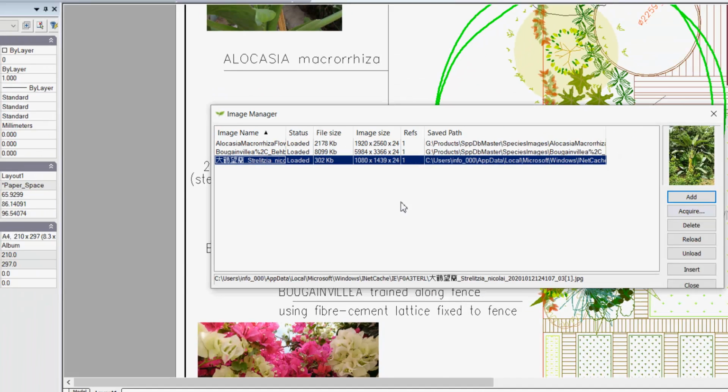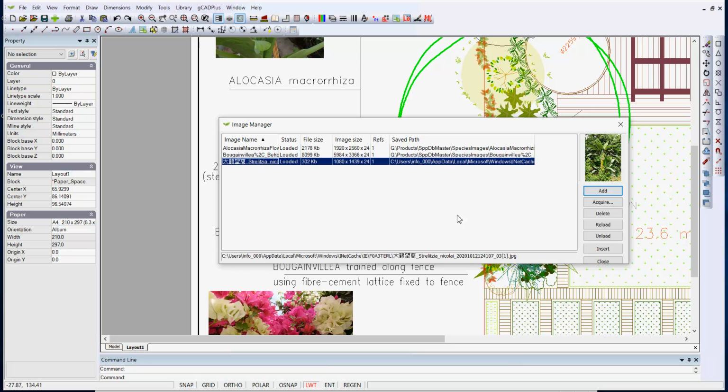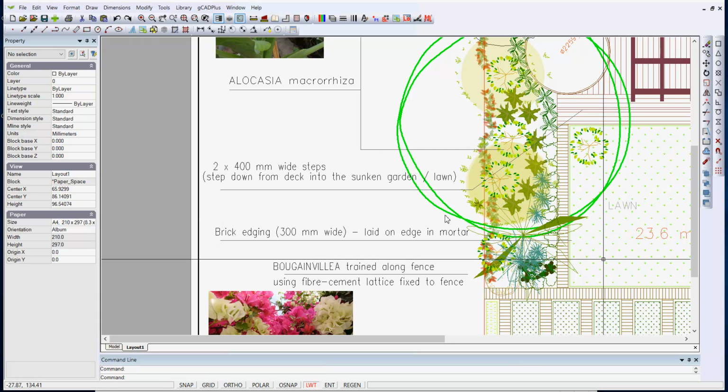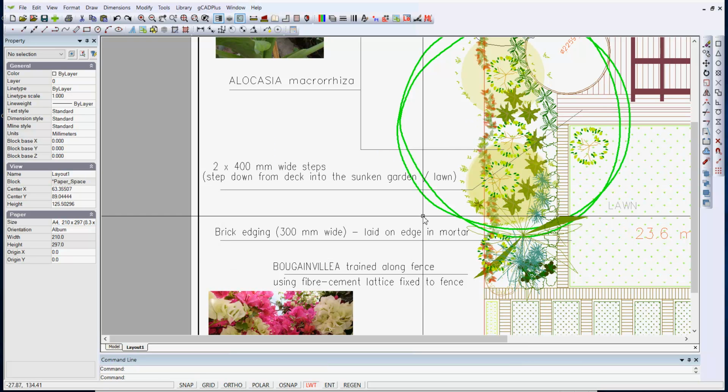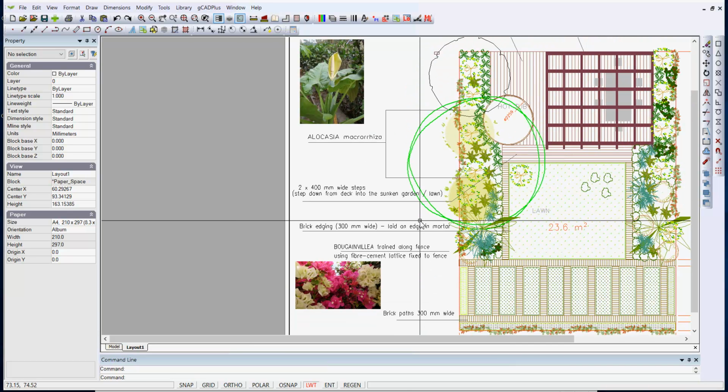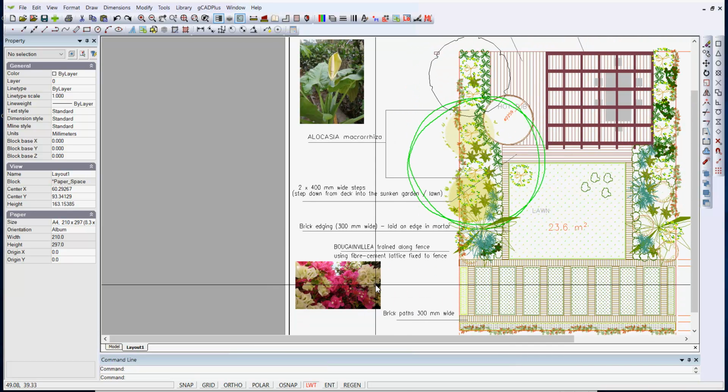So I would be inclined to go back in here and reduce the size. Pretty much all you would need on a sheet like this is a width of about 1200 pixels wide. So I'd be using IrfanView to reduce the size of these images. We're carrying really detailed image files here, and that's slowing my performance.